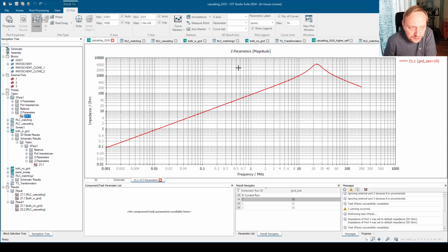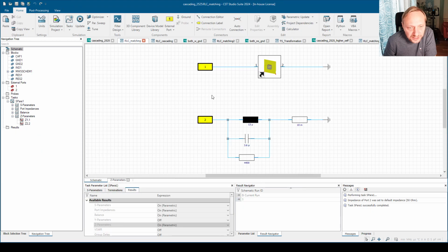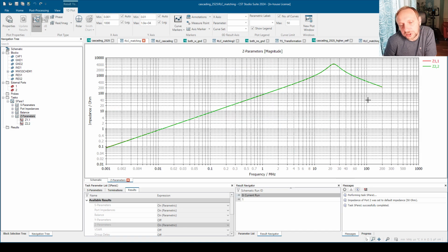That's what you expect from a high-frequency model of an inductor. And when we have this, we can of course take this and match it to an RLC model, right? So this is the high frequency parasitic model of our inductor, which here has 13 microhenry and a parallel capacitance of 3.6 picofarad. I match these values to make sure that the impedance of the inductor, as you would measure it, or which is contained in the Touchstone file, matches the impedance of my RLC model. And if we look here at the Z parameters, you see they match perfectly.